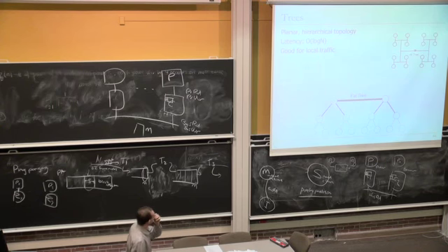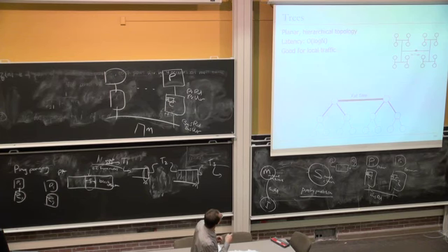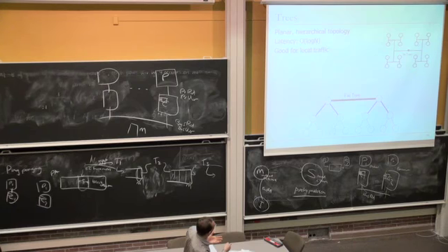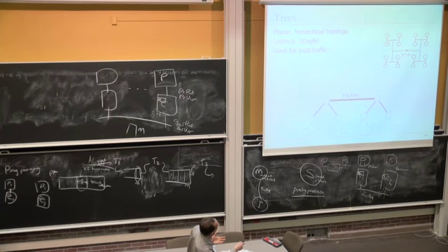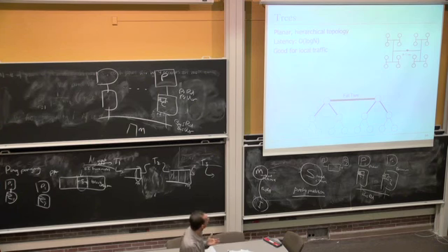Okay, there are other networks which we will not go into more detail about, but trees are some other networks. Well, we all know about trees, right? And this is a hardware tree, if you will. These are the connections that you have. And this is a way of laying out on chip. So if you look at the tree, maybe it looks like it's terrible to lay out, right? But you could actually lay it out this way, and it could be irregular, right? Latency of the tree is O(log n).